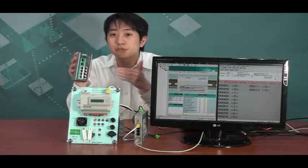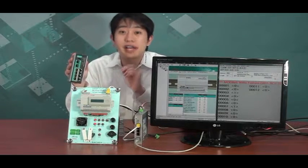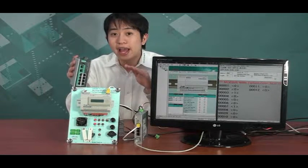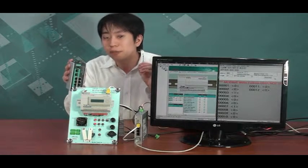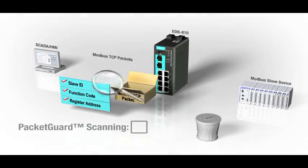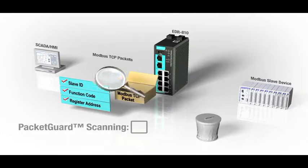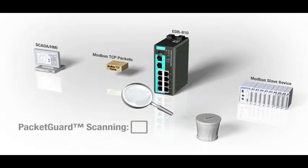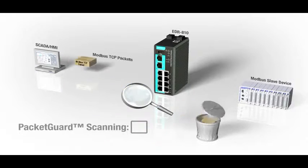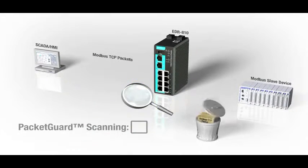An industrial secure multi-port router. Now, the EDR-810 has a built-in firewall and VPN functionality. And critically for industrial networks, it also adds deep scanning of industrial Modbus packets, what we're calling Packet Guard. Packet Guard performs deep inspection of every individual Modbus TCP packet and verifies its slave ID, function code, and register address. Modbus packets that do not meet its requirements are dropped. This adds one more layer of protection on the application level to an existing firewall.